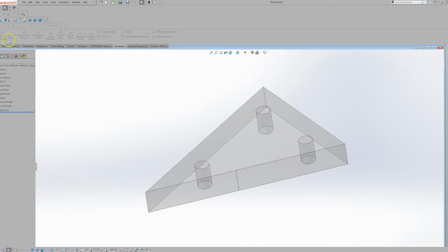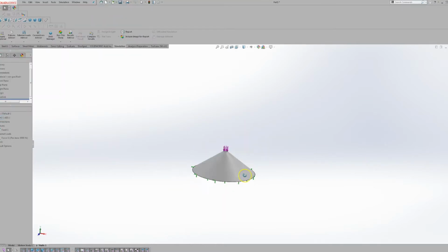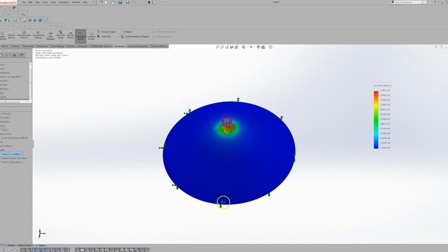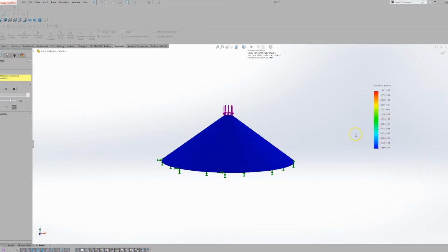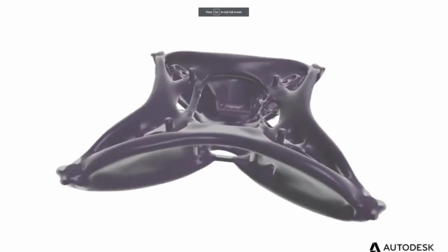The traditional workflow is to design an object, draft it out in CAD, maybe run a finite element analysis, we'll call it FEA from now on, and look at the results of the FEA, be that von Mises stress criterion as it is here, but it also might be any number of other stress or displacement measures. The designer then will typically make changes to the part to optimize for whatever conditions he's trying to test for in the FEA software. Now, the difference between this and algorithmic design is it basically takes the designer out of it once they've specified the boundary conditions.